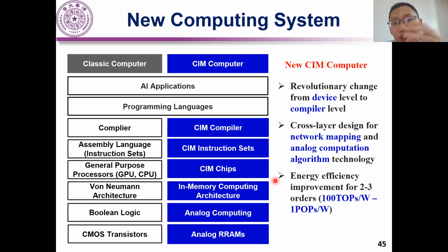We just design a chip where only the input is changed. For these spiking chips, we do not need a DAC for the input. We just need to design, I don't know how to say that word in English, I mean the asynchronous circuit. We just need to design a different input circuit. But the RRAM array and the output are all similar.